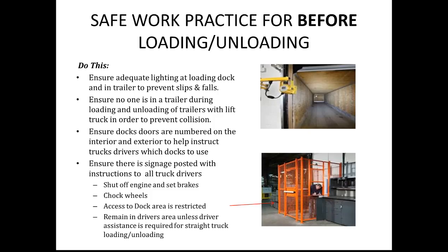It's surprising how many people slip inside or at the entrance of a trailer, and that's often because during inclement weather you get ice or water buildup over that lip of the trailer, and the seals often don't function as well as you'd like them to, and that's where people are at risk.